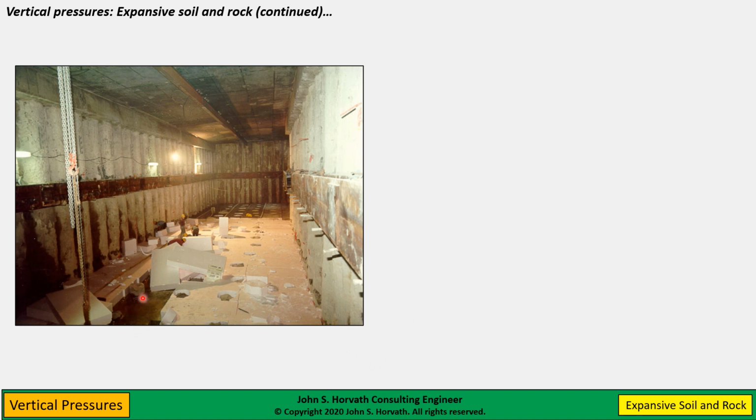And here you see the section of the tunnel under construction, and you can see the deep foundations have already been installed. And what you see here is a geofoam product. This is one of the early products used in the UK that is being installed before construction of the structural slab that will be supported on these deep foundations. Now, this particular product in the UK is colored pink.